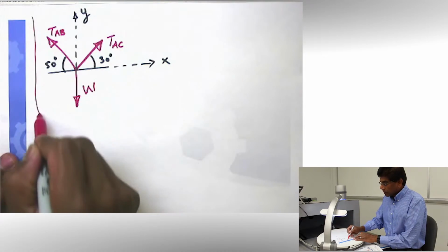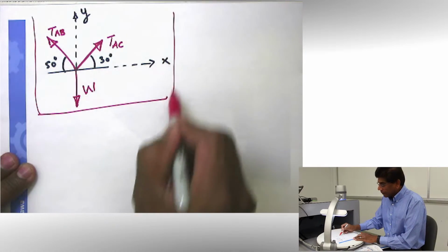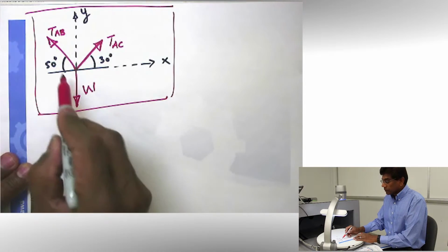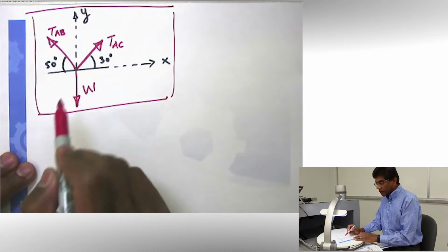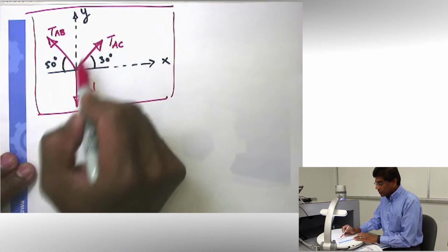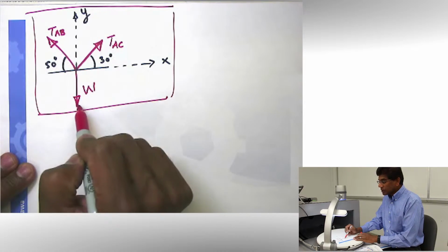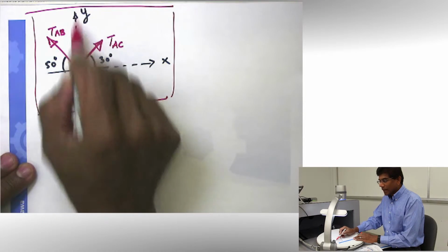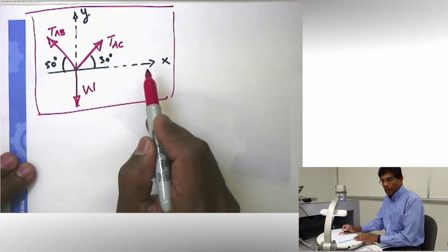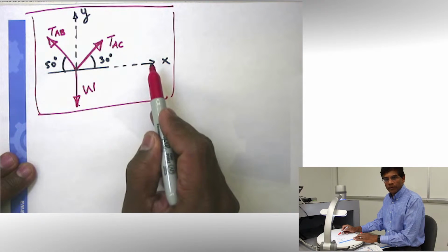Again, steps in drawing a free body diagram: isolate the area of interest, draw a sketch, show all the forces, label all the forces, show all critical information, attach a coordinate system. You will be able to download a handout from the website showing all the steps.